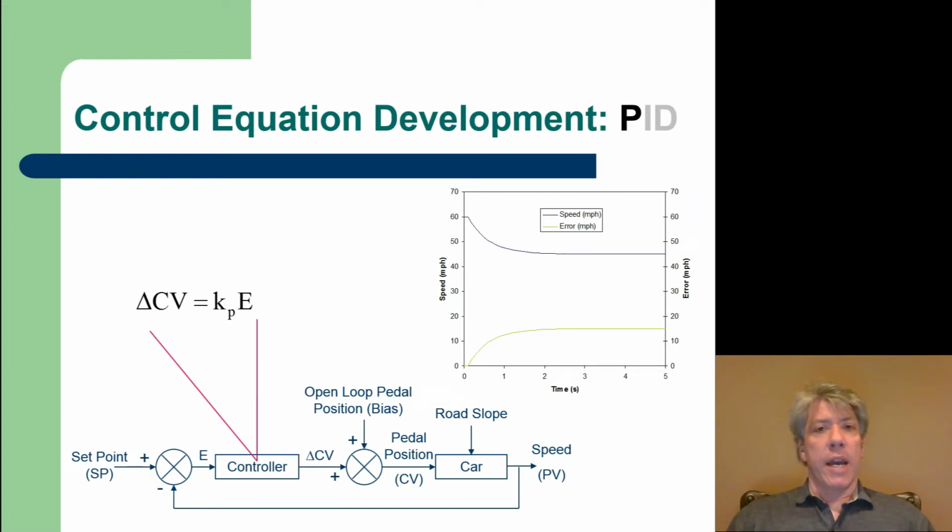So what we might have is, say we're going along at 60 miles an hour, we turn our cruise control on, and we've got a PID controller, well, a proportional only controller. That's what this part is, a proportional control, where the effort is proportional to the error. We've got this proportional controller, and all of a sudden we notice, hey, there's some error. The error is non-zero. That is multiplied by the gain. We'll talk later about how we figure out the gains, but just pretend it's 1 for now, okay? The error multiplied by the gain calculates the change in the gas pedal. So the gas pedal gets pushed down a little farther.